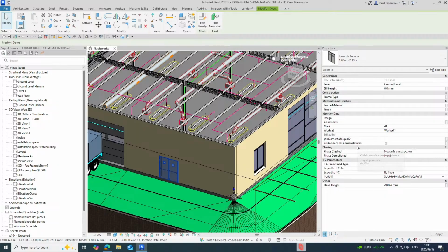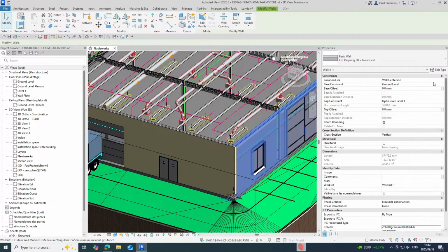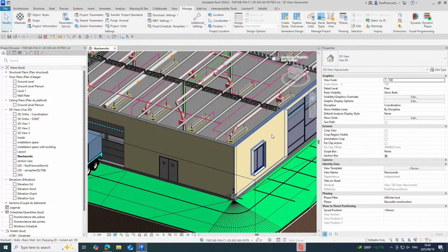And I don't know if that's actually possible, but I think before I do an IFC export, I would actually do that. And in my case, what I'm doing is I'm saying, well, this Revit element has an ID, and the ID is something that I can expose the GUID through something called Dynamo. It's a relatively simple process. We can actually write it through onto the IFC export parameter as well.